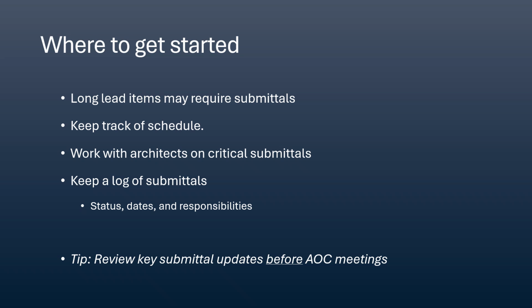It could be that if you have an 18-month project and your mechanical units take 13 months to get to the project site, you can't purchase them until you have approved submittals. And so maybe that's one of the first submittals you work on before anything else. If it's the beginning of a project, your first submittals would probably be a rebar shop drawing or some sort of item affecting the foundation.